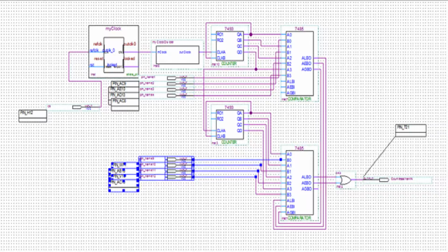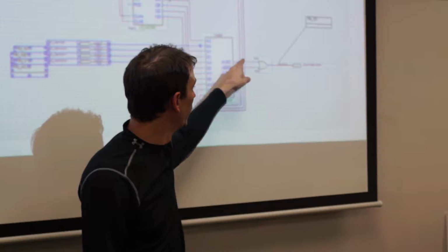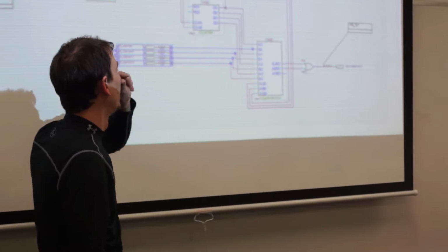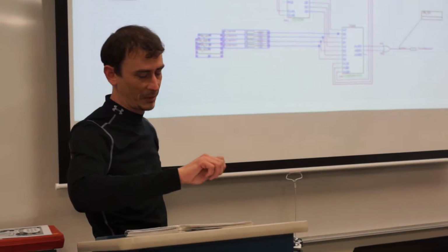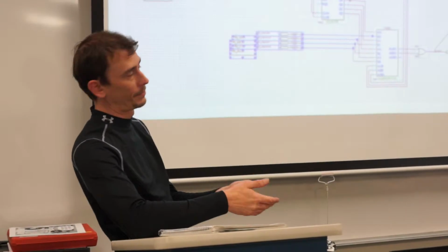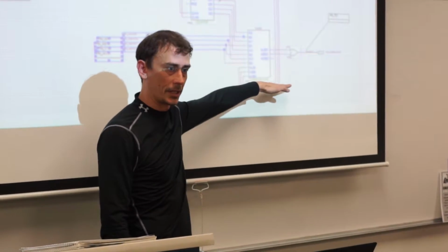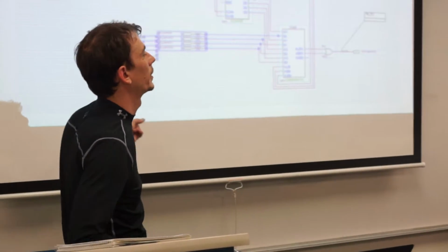I liked these comparators because they give us a low, an equal, and a high output. The PWM coming out here, for example, if we wanted half voltage level out of this, 50%, we're going to turn it halfway up. Whether we're driving a light bulb or a motor, we want half speed, we want half brightness. That means the output coming out here will be high half the time and low half the time. That's what's providing our duty cycle that's going to our analog filter, which I think is the next picture.